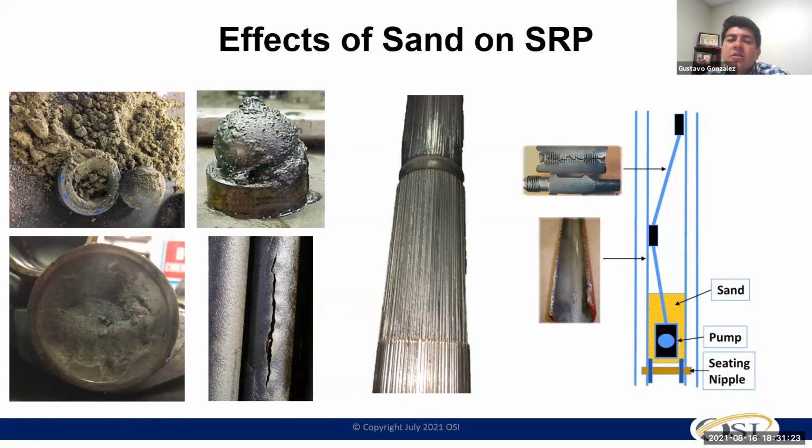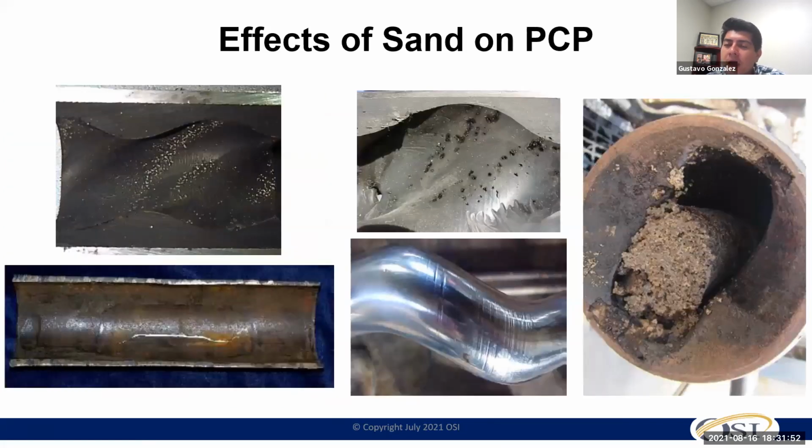And again, sometimes it gets to the point that the ratio, the volume of sand passing through my artificial lift system, in this case either my standing valve, is too high and too severe, because I got a high sand batch passing through and it just gets plugged. So again, that's why choosing the right method to complement your design for your rod pump or ESP is going to be a key factor to increase the runtime.